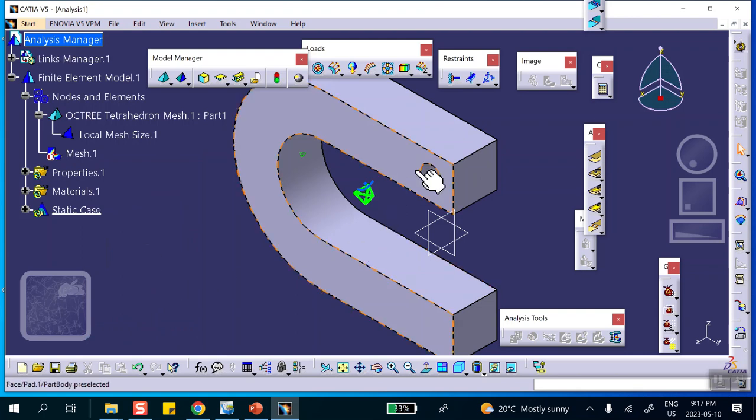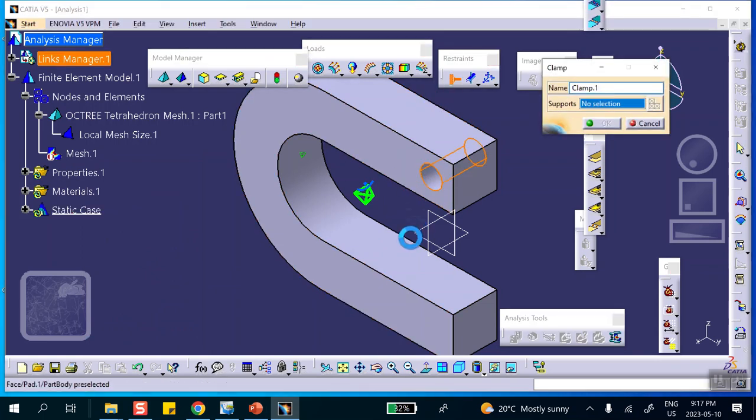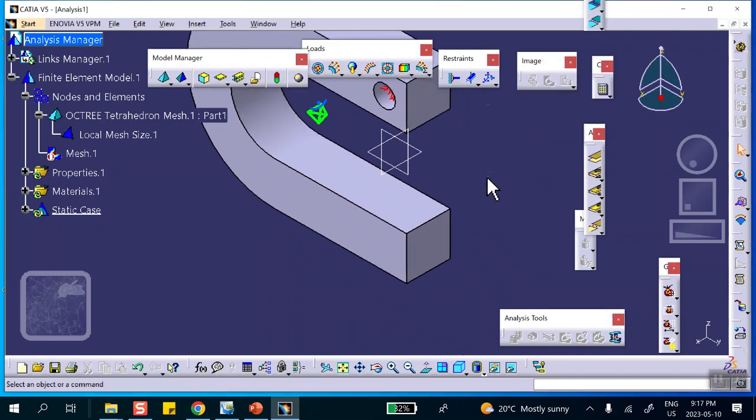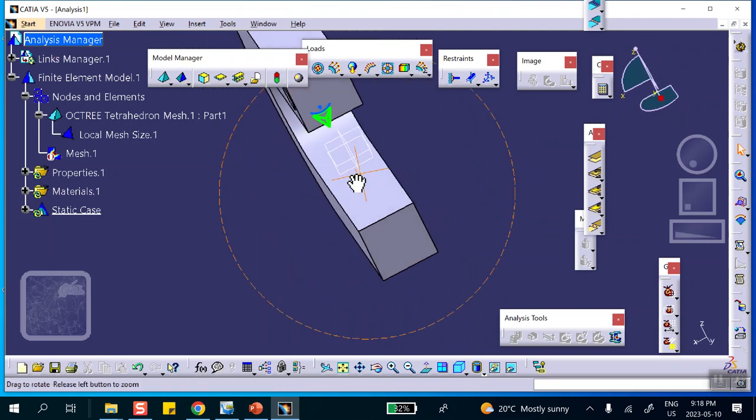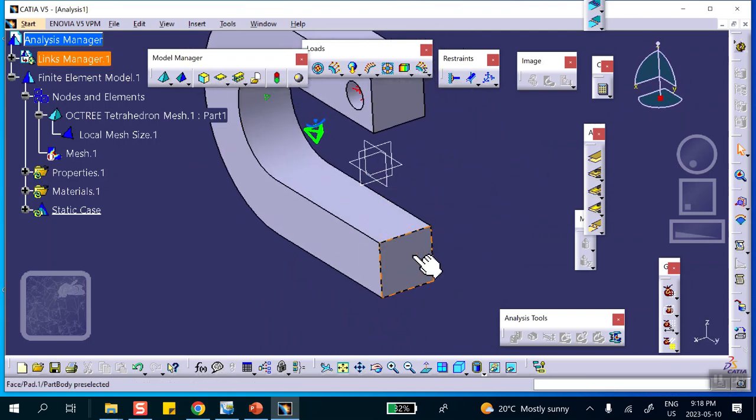All right. Now we know that the inside is clamped, right? Inside is clamped. So you select the clamp and select the inside face. Okay, inside face. Don't select the two edges on the side, because you're not solving the problem that I'm asking you to solve. So that's good. Now, I want to take this face and pull it down. Okay, remember, we are not using planes of symmetry here. I'll come back and do that later for you. We want to pull this face down somehow. Every point on it moved by a 100th of an inch. Question is, how do we do that?